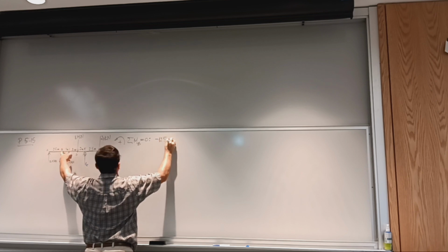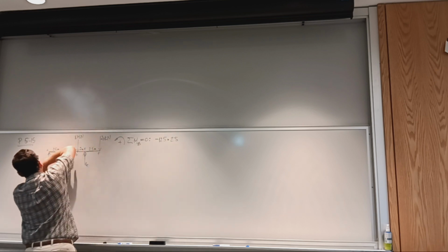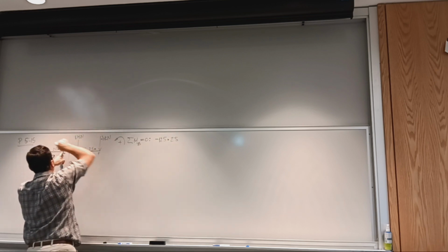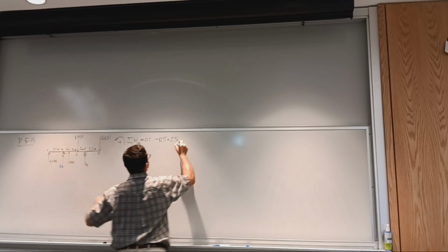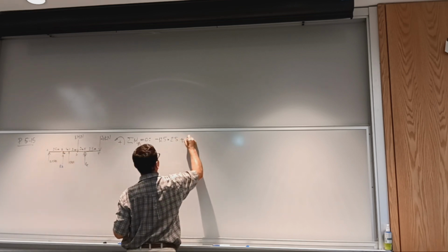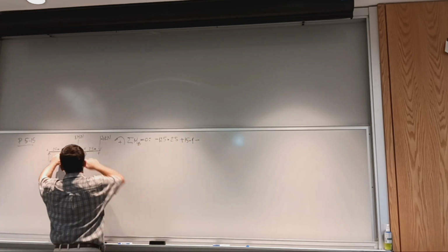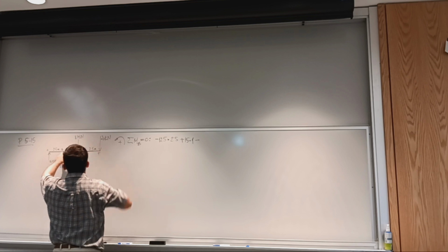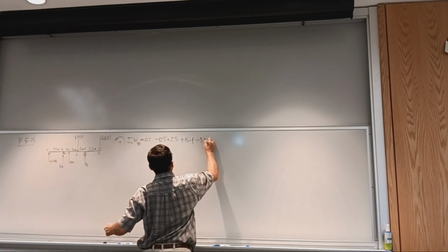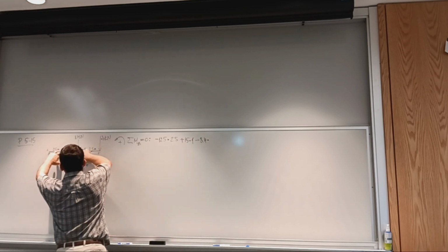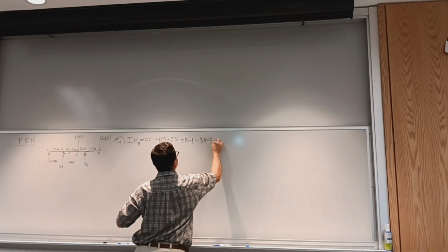So I have 12.5 multiplied by 2.5. And again, this is negative because I assume counterclockwise, so negative. And then I have a positive moment due to the force at C, so there'll be positive 15 multiplied by 1. All right, and then I have a negative moment, which is negative 8.4, and the arm of the force is the distance from B to D, that's 3 meters.